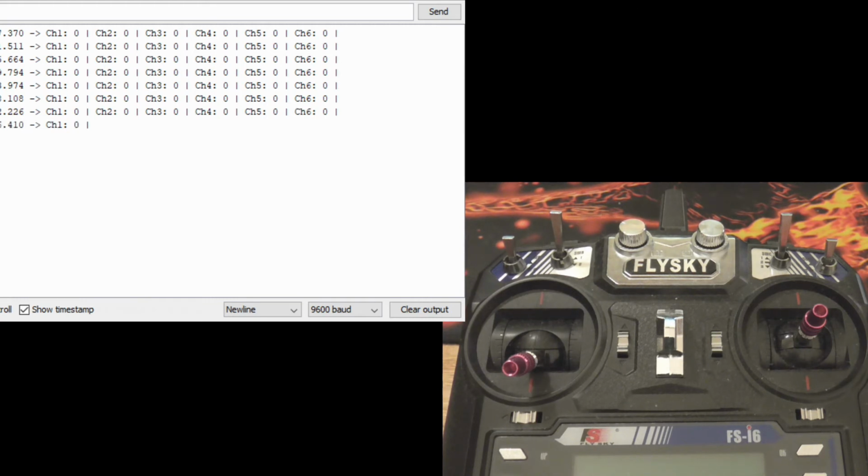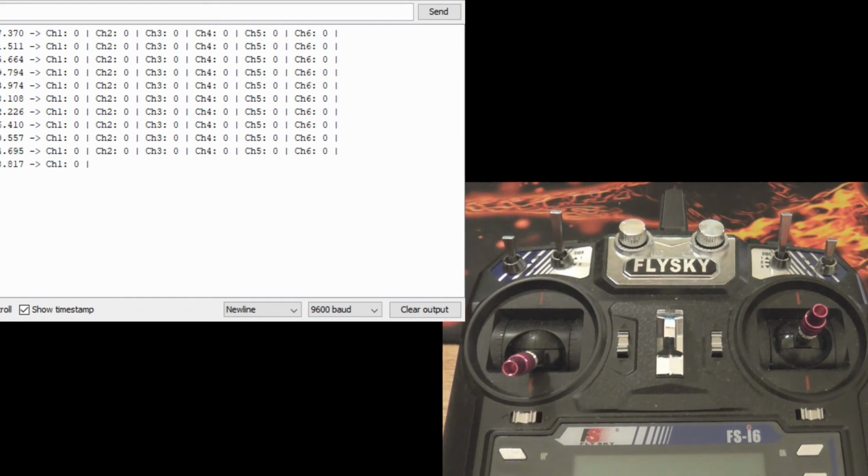I will use this a bit later to actually detect whether or not the transmitter is turned off or on, because if it's off, I want to throttle how often I'm checking for new signals, just because I don't want to continue running through the channels to try and read values if the transmitter's off. So I want to throttle that back and check it less often to save some power.